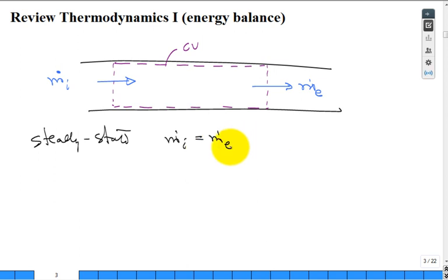All right. Now we can also have something coming across the wall of the pipe and into the fluid. And they use in Thermo 1 this big Q dot symbol. What is that? Rate of heat transfer. What would be the typical SI units? Kilowatts. Yeah, kilowatts. And then they also have maybe something with the shaft, W dot out of the control volume. What would that be? Some power, some energy transfer that's organized in the form of work.